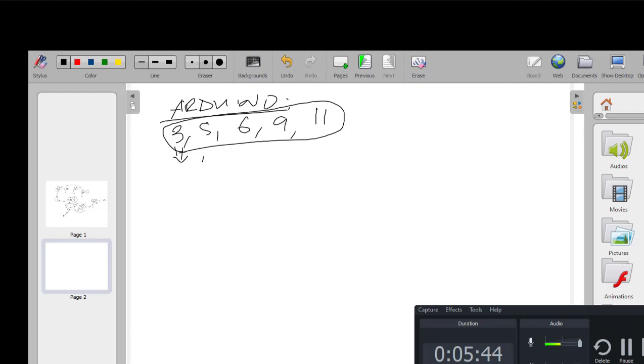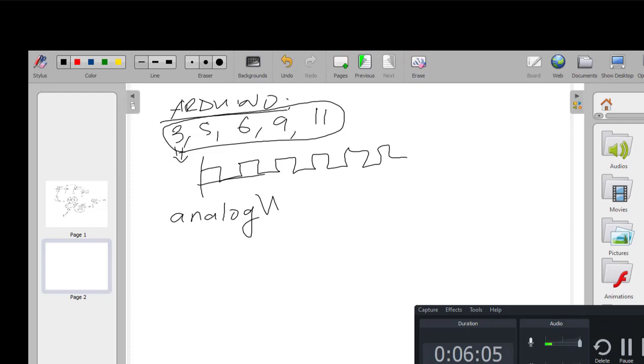Now, what we mean is that these pins can produce a signal that looks like this, depending on how you do the configuration. So now real quickly, I just want to show you that for us to be able to do PWM on the Arduino, there is a function called the analogWrite command. What the analogWrite command does is it takes the value of the duty